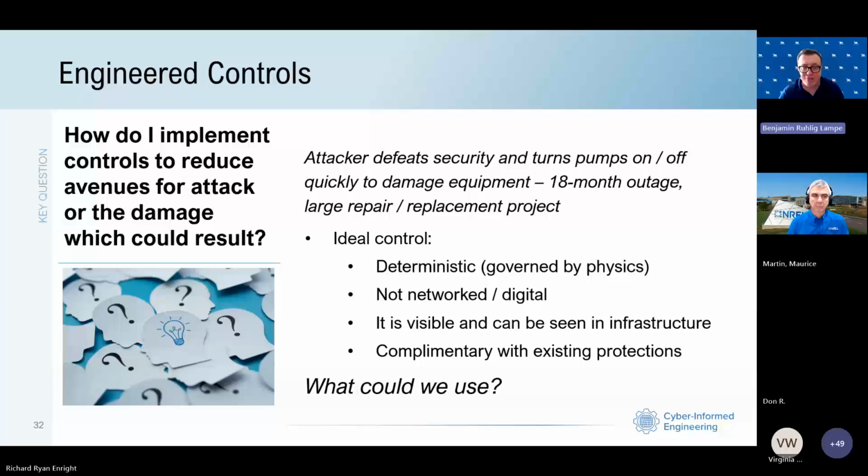And that time enforcement mechanism is not cyber susceptible, like the logic that might be in the PLC is cyber susceptible. So you're taking advantage of multiple dimensions to help protect that critical function that's being expressed here in this pump station, and knowing that control helps be deterministic, governed by the physics of the materials in that relay and mechanisms like that.